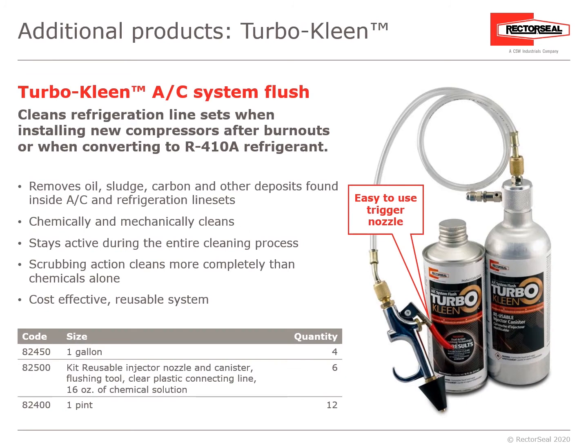Some additional products from RectorSeal, we have TurboClean AC System Flush. It cleans refrigerant line sets when installing new compressors, after burnouts, or when you're converting from R22 to R410A refrigerant systems. It removes the oil, sludge, carbon, and other deposits found inside AC and refrigeration line sets.